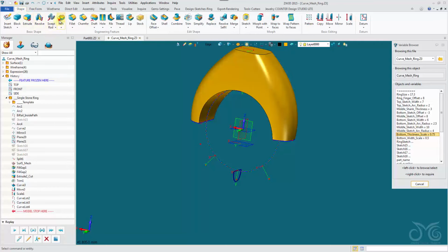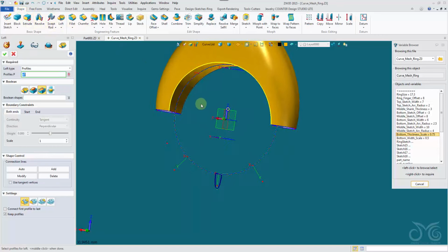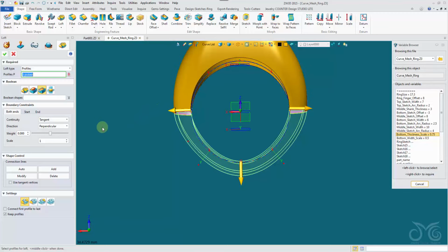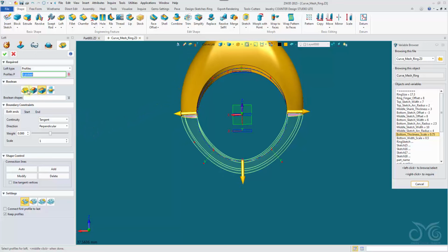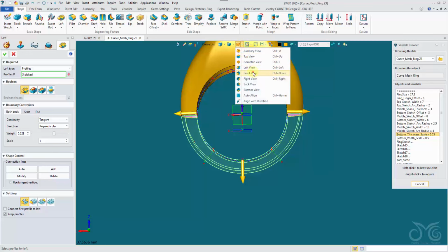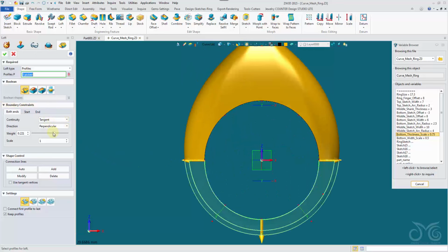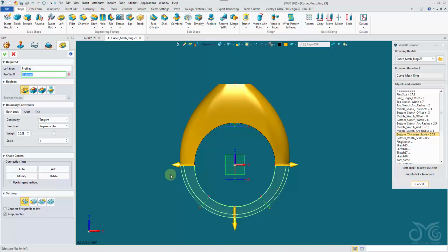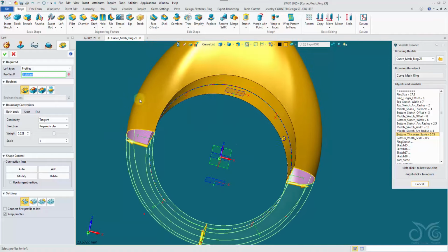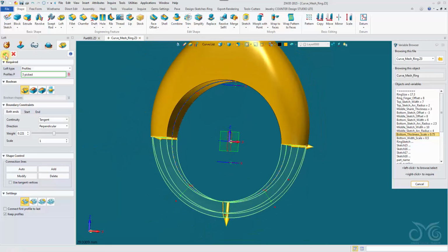Finally, shape, loft, lofting from curve lists, 1, 2, 3. Okay, let's set this as adding as a base. Now we can play with our tangencies to get it lined up nice. Come to a front view. Okay, the reason we're doing a loft is so that we're keeping the tangency, the flow from our upper half to our lower half. Let's confirm it there.